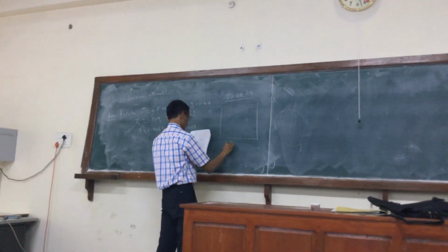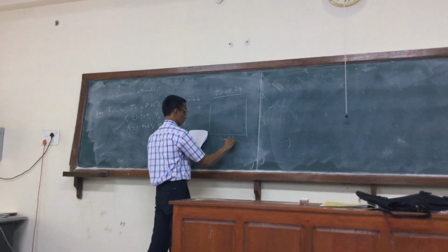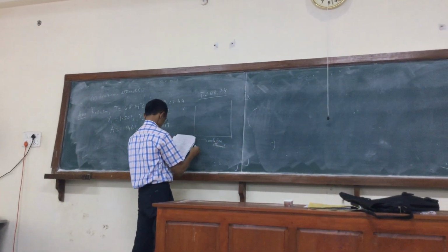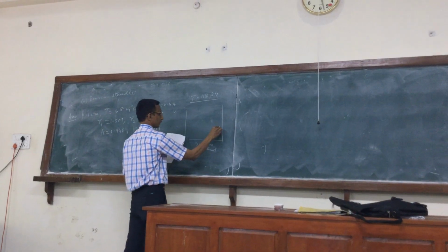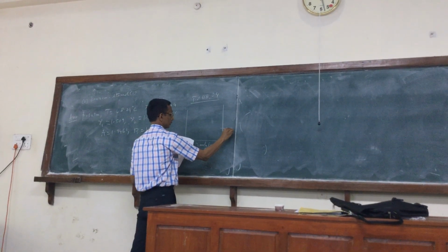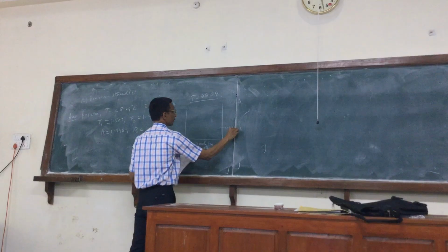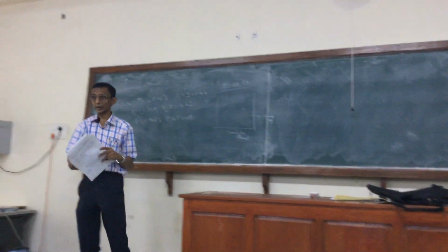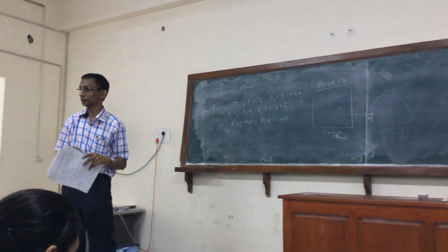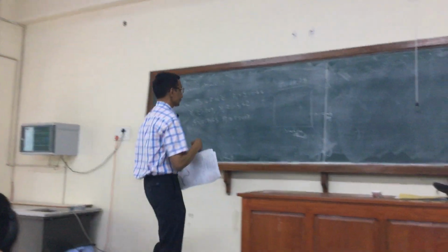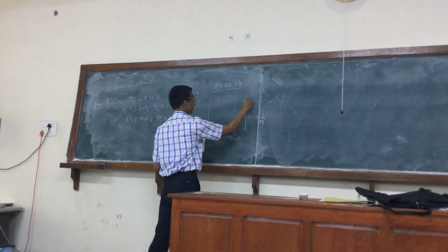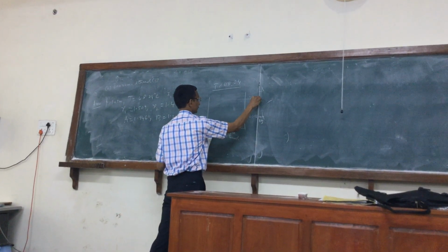So I have here the mole fraction of ethanol, which is component 1, and its saturation pressure at 68.24 can be calculated easily from the Antoine equation. If you know how to approximately sketch the curve, and clearly let's say this is 760, at which it has an azeotrope.